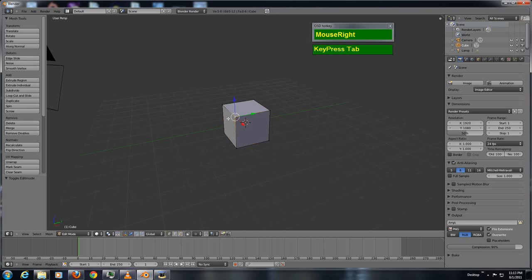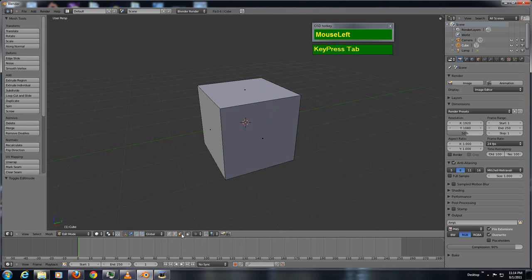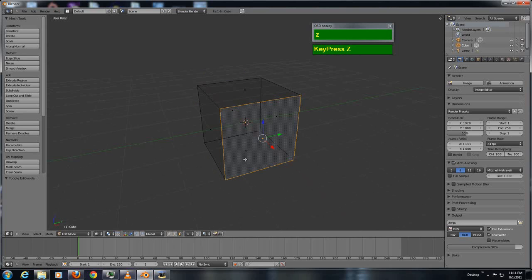There is the vertices, and then I'm now changing the selection mode to edge, so now I can select the edge, and of course the faces. So notice as I switch between the selection options, you see that for faces usually there's a black dot in the center here. Let me go to wireframe mode by pressing Z. By clicking on the black dot, you can select the individual faces, right? And in fact, holding down shift, you can turn on all the selection modes at the same time, but this can get rather confusing.